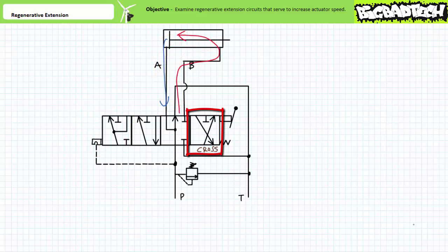Finally, when the manual lever is moved in the opposite direction, the valve shifts into a cross-connect position that retracts the cylinder. The valve also features a pressure-released mechanical detent upon retraction. When the cylinder fully retracts and pressure rises to the adjustable kick-out pressure, the detent automatically releases the valve to the deactivated spring offset tandem position, again keeping the main pressure relief valve closed.